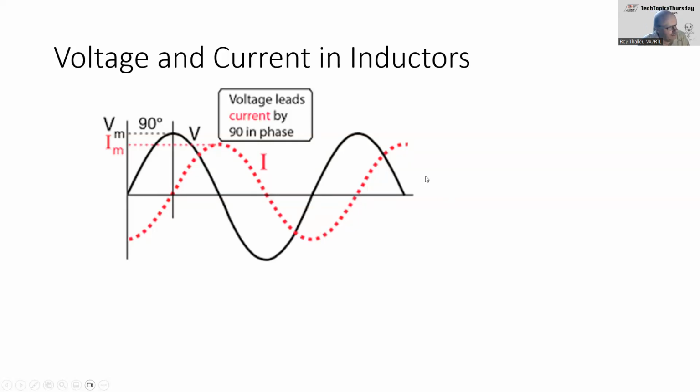And in the capacitor, it's just the opposite. The difference between these two sine waves is known as phase. In this circuit, because we just have an inductor, it's 90 degrees out of phase. If we were 180 degrees out of phase, this curve would cancel this curve and we would get a straight line.